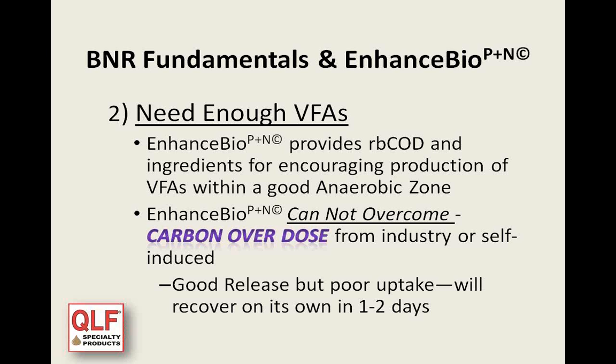As far as one of the things that I found working with treatment plants over the course of the last year and a half is there's a thing that I call carbon overdose. You can actually overdose your system with carbon, either yourself by adding too much of our product, or if you are hit by a loading from an industry that has high COD.